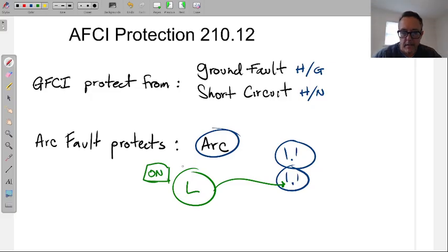So when this is on, whatever load it is on, and it's generating some amperage, the more amperage, the more arcing. All right, if this is 2 amps versus 20 amps. Let's say you have 5 amps, a light plugged in, drawing 5 amps. If you don't turn this light off and you just unplug, as you're unplugging, you are disconnecting 2 points that have current running through them.